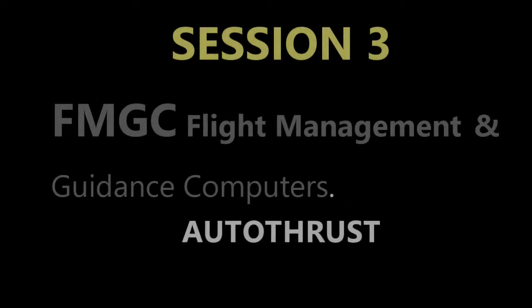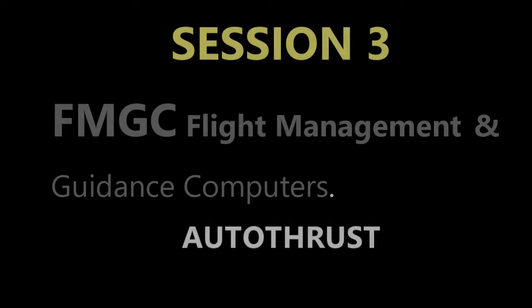And then you have, of course, the engagement of it can be manual or automatic. Okay, on auto thrust engagement. Remember I said one of the engagement push buttons is your ATHR. Okay, that's your auto thrust. So you have that on the FCU, and that can be engaged again by pressing on it. Now you can also have an automatic engagement of the auto thrust function, and that's when the AP flight director is engaged in takeoff or your go around modes. Okay, also in flight, when you have an alpha floor that's detected by the computers, then you know that's going to certainly kick in, right?